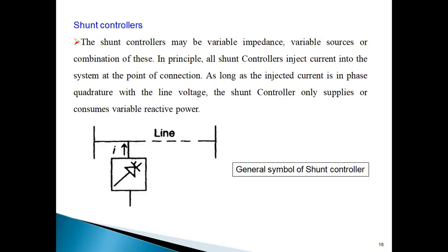So what we conclude here is, in case of a compensated system, we are having power flow twice, the power has been doubled. Therefore, that is the maximum power, 2V square by X. Therefore, we make a conclusion that whenever we do a midpoint compensation, the power is being doubled. I hope you will appreciate this point and you will all agree with my point.